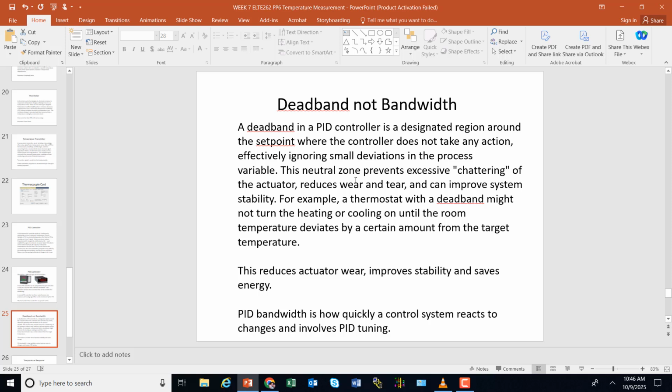And that's what we talked about. On your house, if you set the thermostat to 70 degrees, it overshoots a little bit to 71 before it shuts off, and it probably goes back down a degree lower, to like 69, before it turns on. So there's a couple of degrees of deadband in there where it goes back and forth. Otherwise, if you made it too accurate, your heater would just be clicking on and off, on and off, trying to keep the set point. And you don't really need it to be that precise.